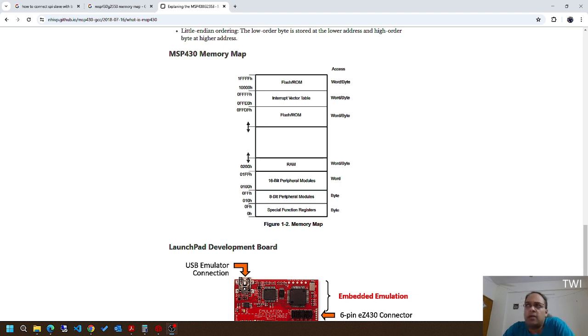The main concept here is that I'm going to take a very basic microcontroller, the MSP430 series, which is a 16-bit MCU from Texas Instruments, and show you how we can do the in-application program update for those products that you've already designed in a lower memory footprint microcontroller. That can be some ST micro or PIC or AVR or any kind of MCU which supports flash programming.